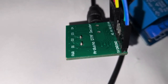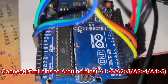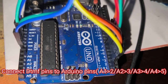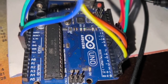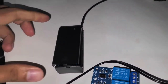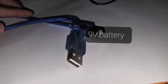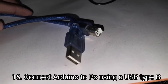The DTMF pins A1, A2 and A3 are connected to the digital pins 2, 3, 4 and 5, and the pins 6, 7, 8 and 9 are connected to the inputs of the relay module. Also, the Arduino board will be powered by a 9V battery. The code is uploaded onto the Arduino using a USB Type-B cable.